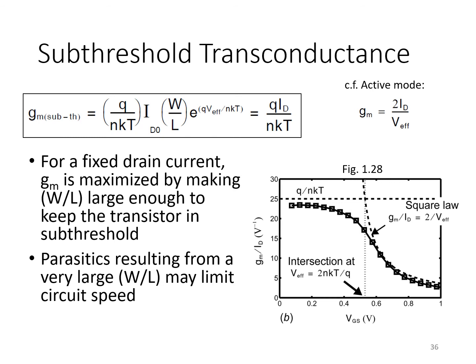The other thing it lets you do is get a feel for and extract the transistor model parameters, things like the value of n, mu n, Cox. All these constants can be estimated by performing simulations. Now you might say, if you have the transistor model for your simulations, why can't you just look those values up directly in the model?